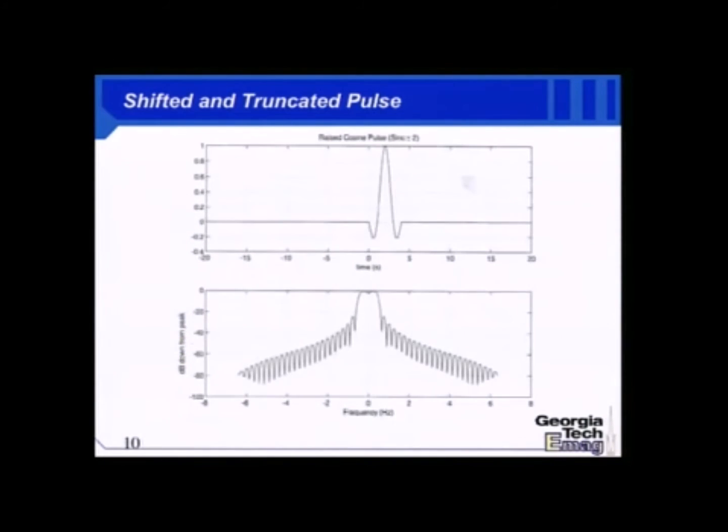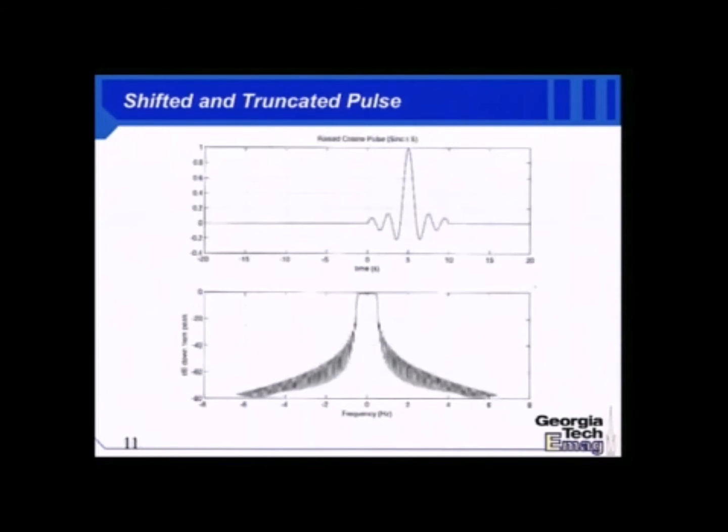However, this pulse only satisfies the Nyquist intersymbol interference criterion if you're transmitting at a rate that's now dilated compared to this pulse. In other words, they may do similar jobs of collapsing frequency content inside your band, but I can put my next symbol a lot closer to the peak in this one. So I can maintain a high data rate. So this is a sneaky way to sort of have your cake and eat it too. Collapse your signal spectrum, but not compromise your data rate. So it's a very insightful question to ask.